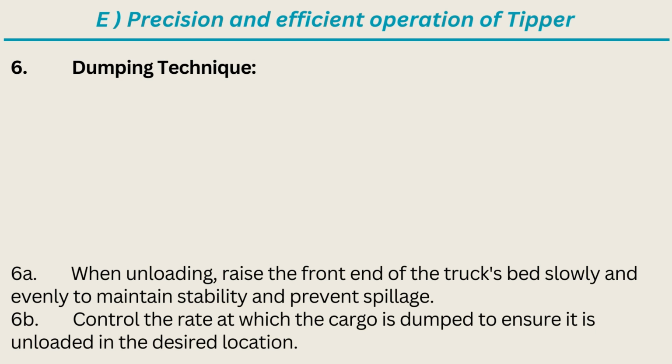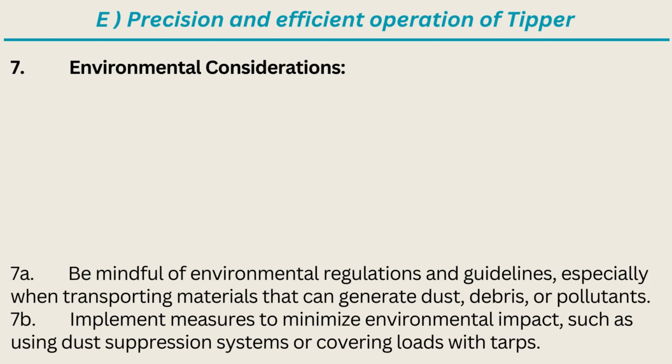6. Dumping technique. 6A. When unloading, raise the front end of the truck's bed slowly and evenly to maintain stability and prevent spillage. 6B. Control the rate at which the cargo is dumped to ensure it is unloaded in the desired location. 7. Environmental considerations.